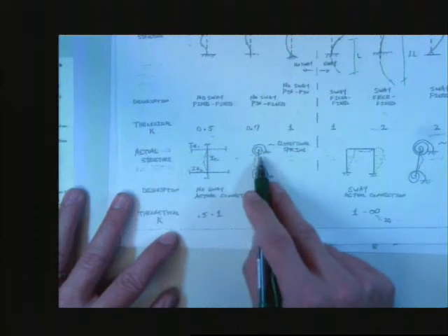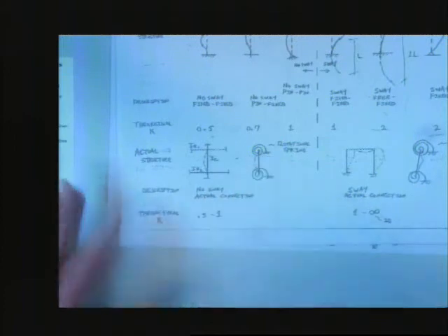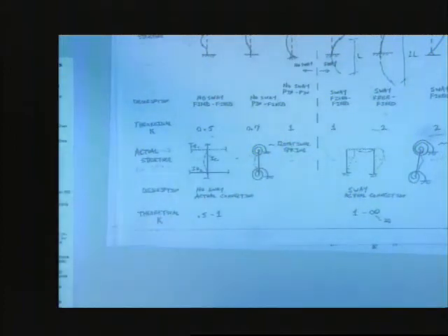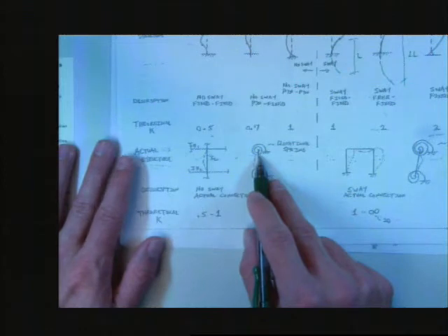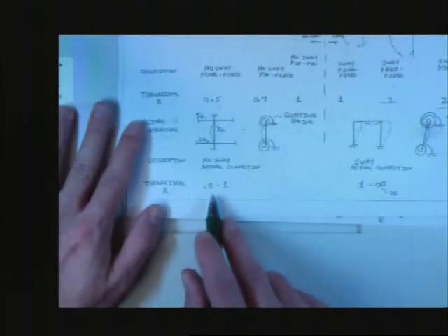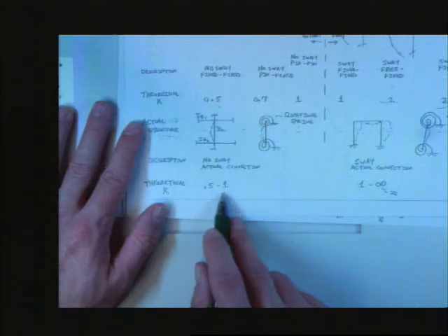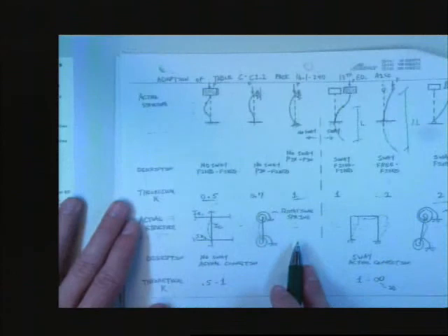They're a rotational spring is what we're going to do. And that's what a rotational spring is. It's a way to live somewhere in between the fixed and the pinned world. We talked about moment connections previously, how stiff they are and all that stuff. It's very similar to what we're doing here. And we'll find out that their answers have to be anywhere between 0.5 and 1. They have to be between these two values, and that makes sense.